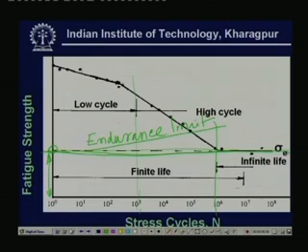Now, this endurance limit of the material, shown here as sigma E, is not always a true constant line, I mean a true parallel line to this x axis. In fact, this is a typical behavior somewhat resembling a steel material. But if we have some non-ferrous materials or alloys, we can expect, again schematically,